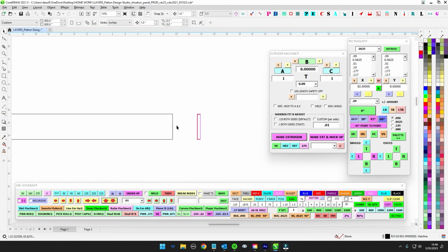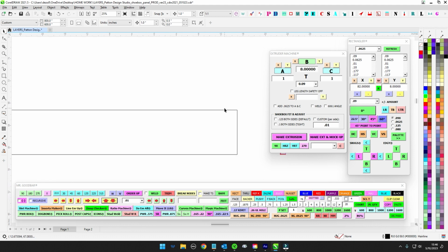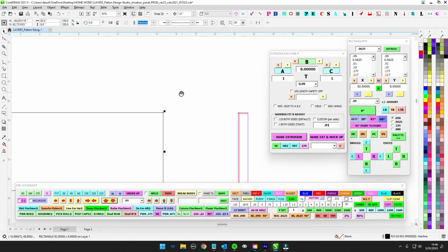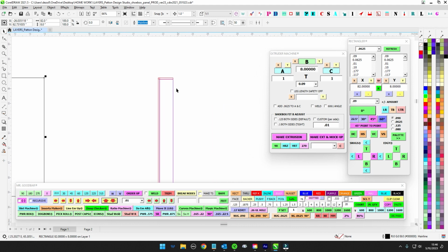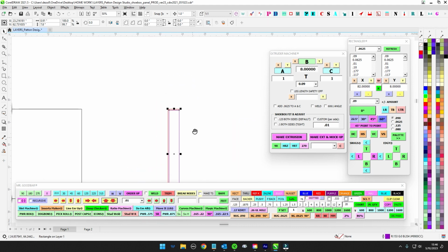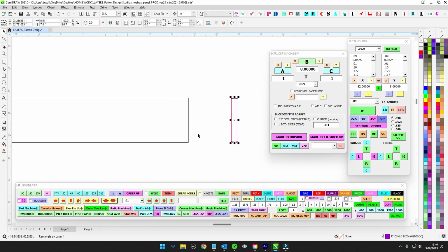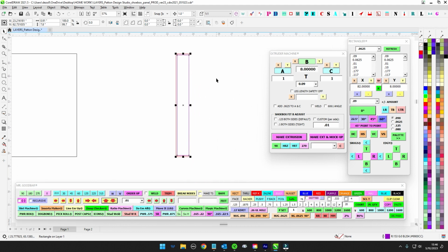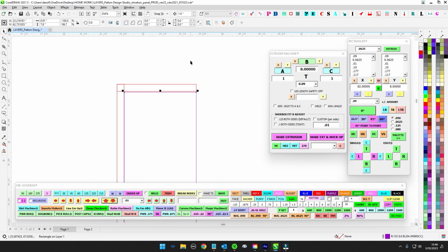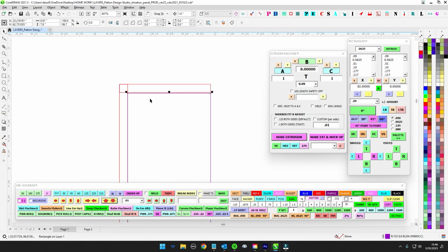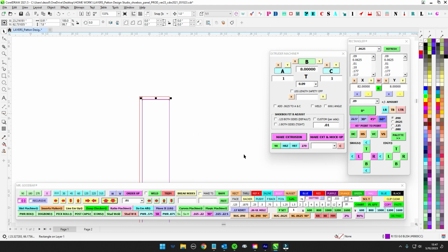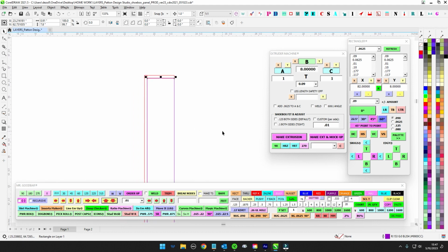So if you want this backer to be on the wall and you want to slide this thing on to where you almost have to use your fist to kind of bump it on, then this is what you want. 0.01 on the top, 0.01 on the bottom, and then you can friction fit it on. If you're doing any sort of fabrication like that, generally I always bake in 0.01 for clearance on these things. And sometimes that's not enough. It just depends on the bending. It depends on the weather. I don't know, anything.